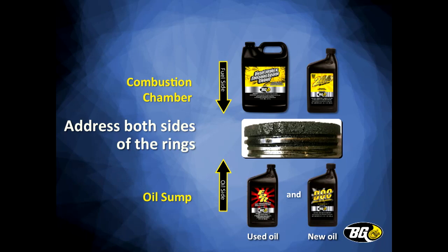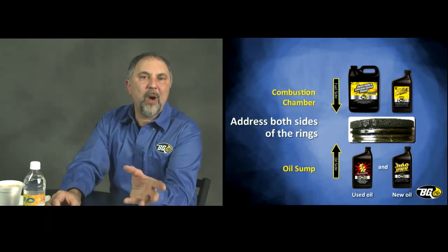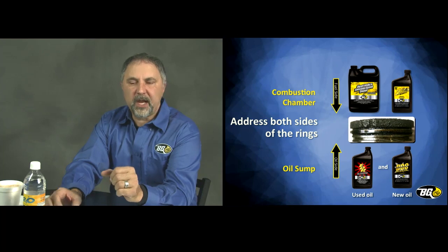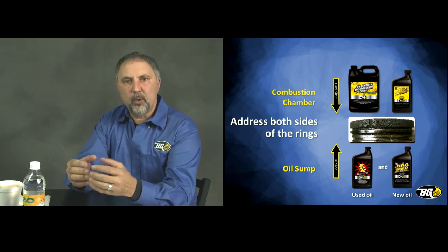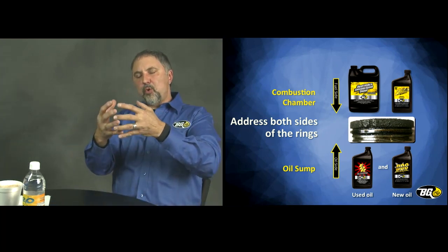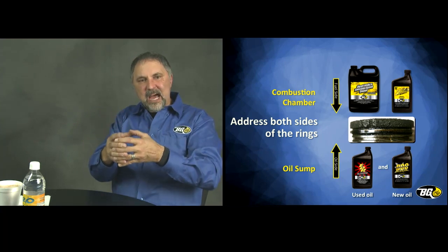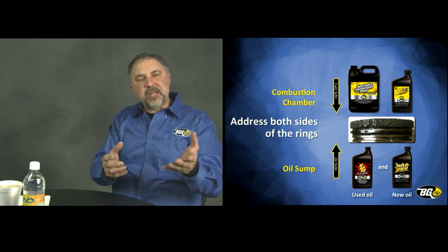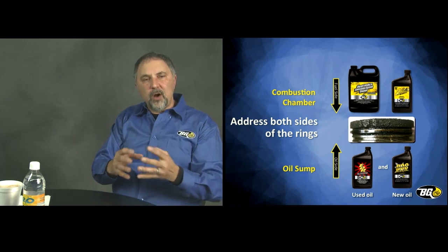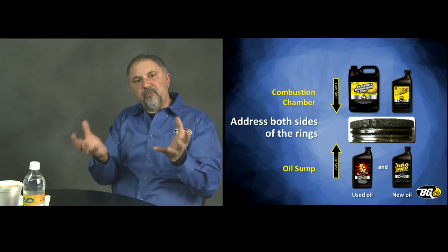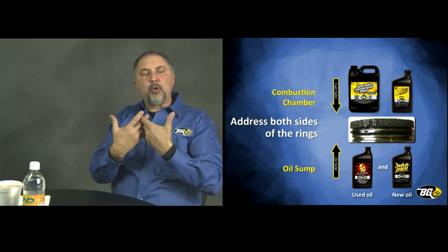Now, DOC itself, the way I like to describe it, if you can envision in your mind's eye, cold flow improvers are paraffin wax in number 2 diesel fuel. And you get wax gelling on a filter. When those wax particulates start to coagulate or collect together, it plugs the filter up. That's the same thing our DOC does for the engine oil. It has soot scatter technology, which prevents those things from coagulating and creating hardened carbon deposits that'll cause damage like you see there in the picture.